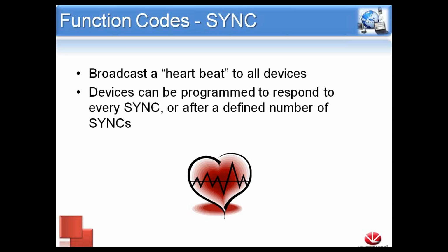Normally with, for example, Modbus or Modbus IP, we have to connect to each device individually, and we will go in order, so 1, 2, 3, 4, 5, etc. With CANOpen, we get all that information at the same time. Everything is synced up to a heartbeat.